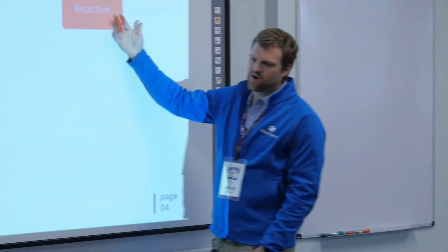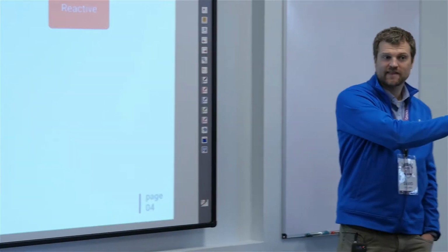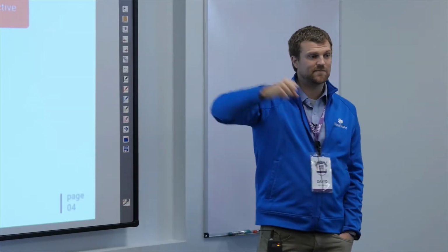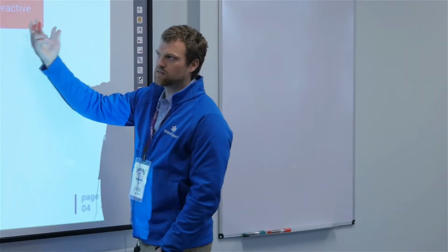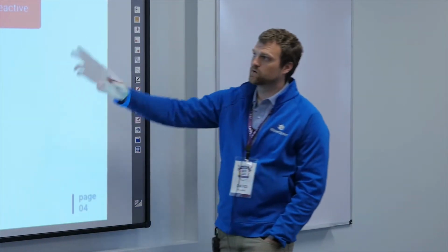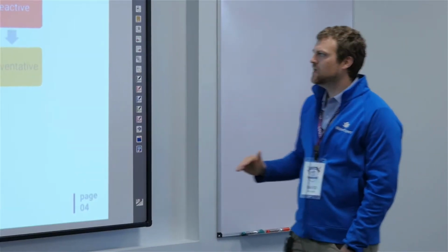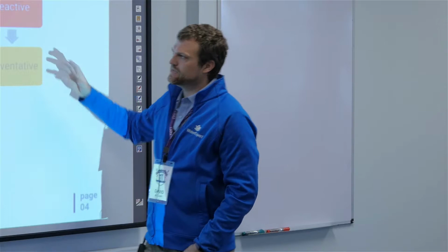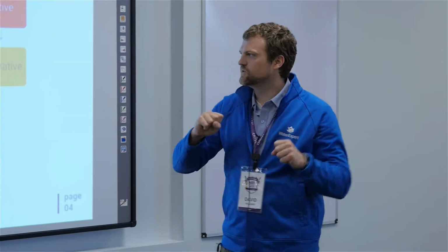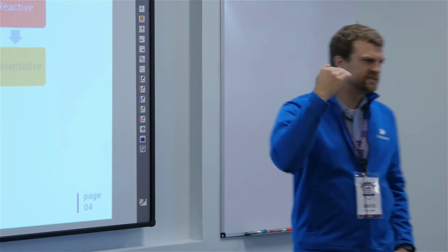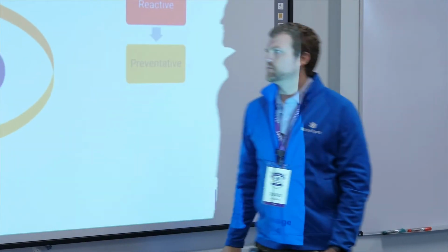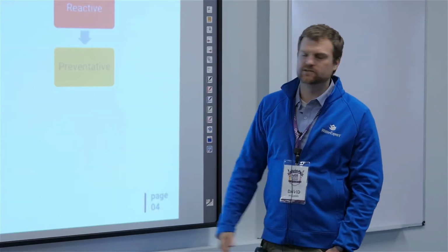And this is harmful in a couple ways because if you haven't procured that particular critical component, now you have to pay a fortune to get it here, overnight it, whatever it is, right? And so this ends up costing a lot more than a different approach. So the next stage of evolution would be preventative maintenance, right? So this means you've read that manual cover to cover and you've extracted all of these maintenance schedules and this information so you can come in and actually schedule stuff before it breaks, right? So it tells me every 500 hours or every 6 months I'm supposed to do X, Y, Z. So I come in and I try and prevent things from happening. This is the timing belt on your car type of situation.